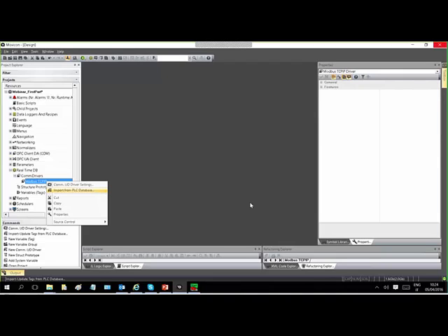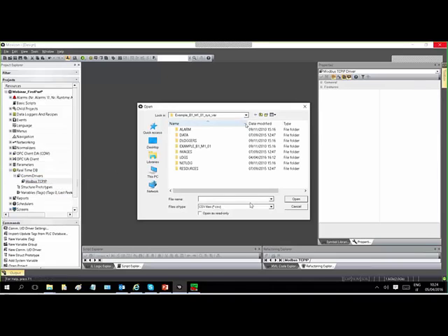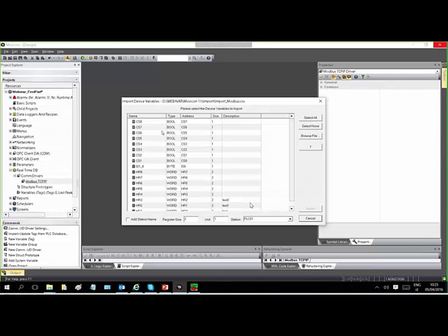This could be good. You can export from the PLC controller logic the whole list of the tags, and then in the SCADA you can import. So with a few clicks, you will have all your tags here. Import from file. Modbus is not so smart an example because it requires a CSV, for example.